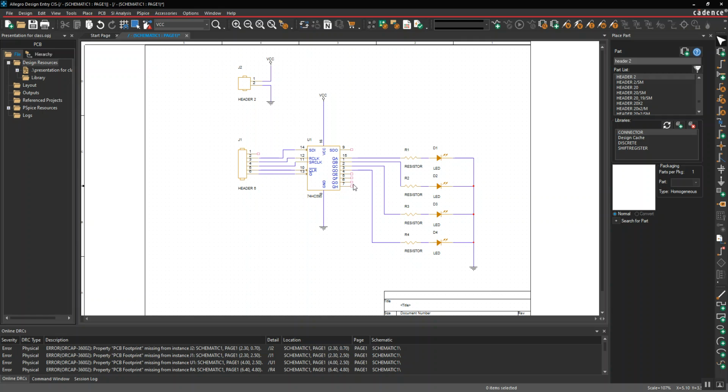There's a reminder that you're going to want to non-connect any pins you're not using. So hotkey X or this little no connect over here. And then for the net alias, this might be a time when you would want to use one, even though this is part of the same package over here. And instead of running this all the way around, you could just do W or select the wire. It needs to have a lead to where this disappears, so just a small wire.